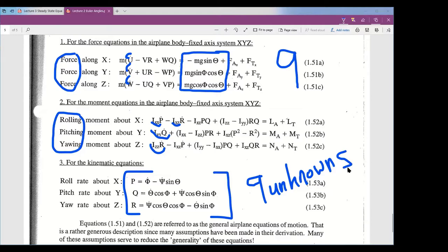They're differential equations. Piece of cake, right? Differentially, in fact, they're ordinary differential equations. Here's du by dt, dv by dt, dw by dt. The problem is we've got v times r, and that's a product of 2 motion variables. Same thing for w times p, and all the others I'm not going to circle. Here we got p times q, p times r. Those are called nonlinear terms because it's not a number times a variable, it's a variable times a variable.